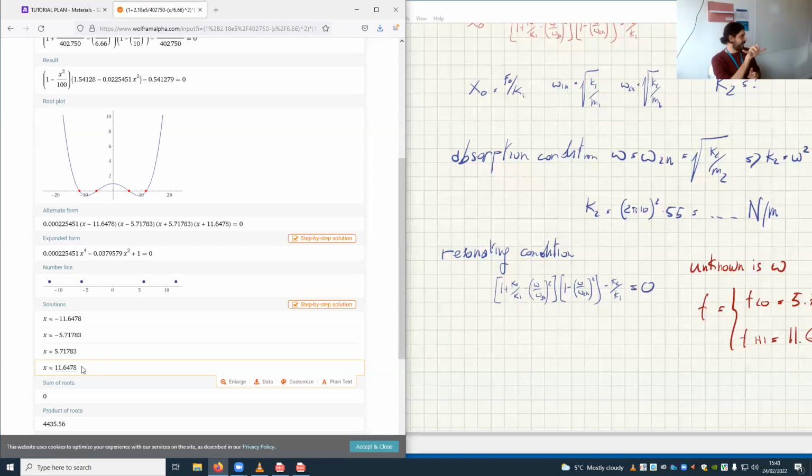If you want to increase that range, then you need a different combination of K2 and M2 in order to give you the same omega, but in order to have a larger range, you have to have a larger mass. So if you increase mass 2, in turn increase K2, you have a much stiffer spring with a much larger mass, so they are still tuned at the same frequency, but now the range becomes larger. So increasing mass enlarges this range. But there's only so much mass you can add, which is freely vibrating. You agree? Otherwise, it becomes a bit unwieldy.